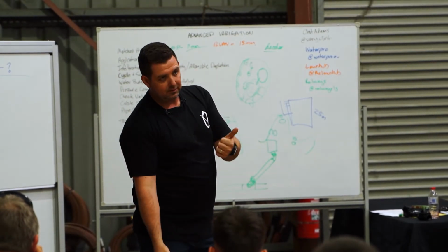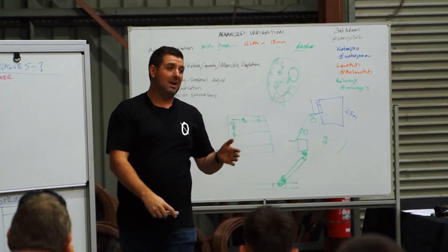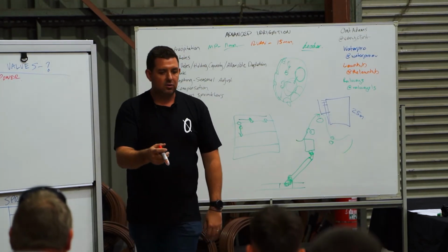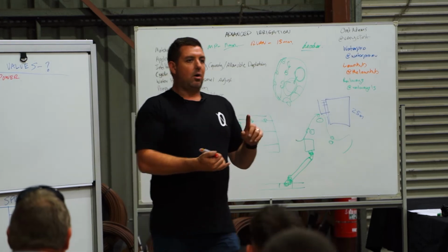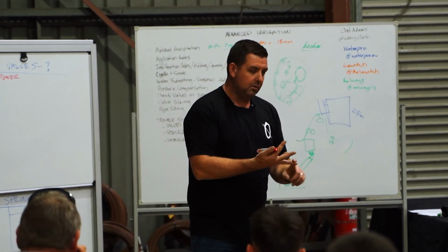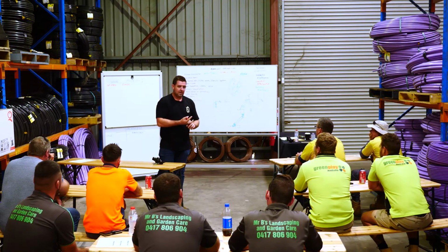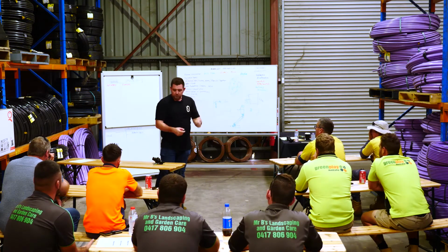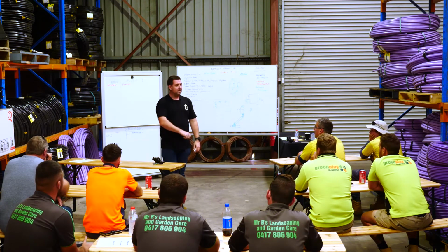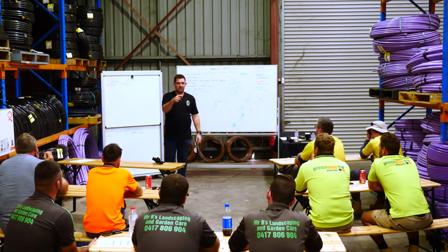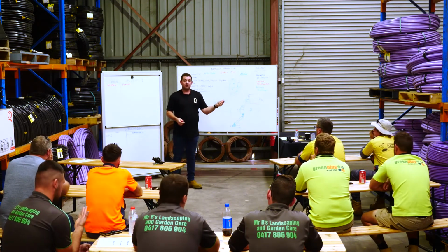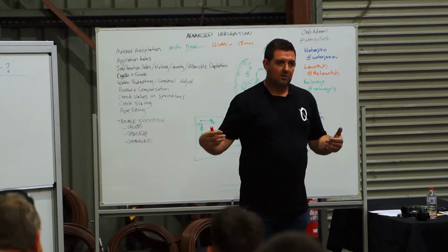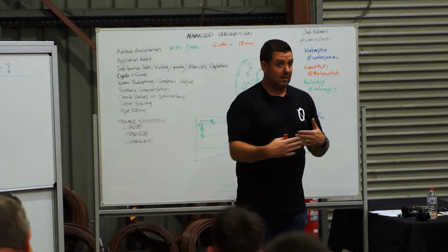It could be not enough electricity, so obviously the voltage is low. It's going to be less likely to be that, as most people are putting the cable in properly. If it's an electricity issue, it's going to be the controller's off, the cable's broken, the wire joins haven't been done properly, it's screwed into the wrong hole, or there's deterioration of some capacity. The cable size might be right, but someone's nicked the plastic and it's started to deteriorate. And when you get that corrosion in the cable, you're going to have the same problem.